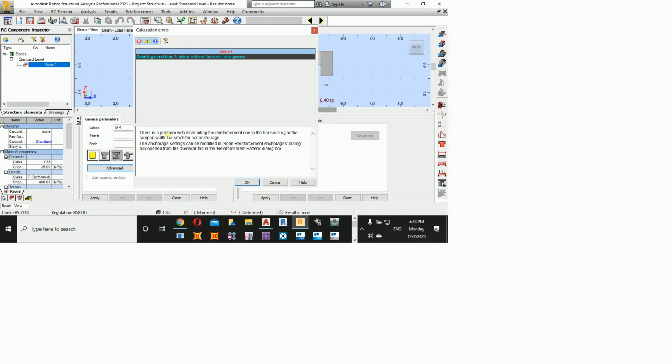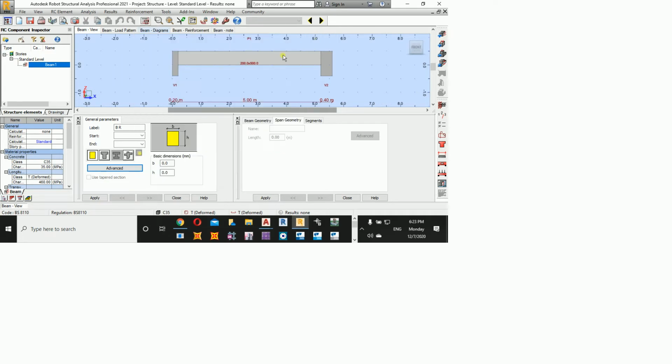Now, if you understand the concept of linking or connecting the beam with another element, whether it's a beam or a column, we need to penetrate the bars inside. They need to go inside. In this scenario, the width is small. It means the width is not sufficient for me to connect these two elements together. So normally, we don't put straight bars. We go for a hook, right? In your scenario, the students have already set the hook.